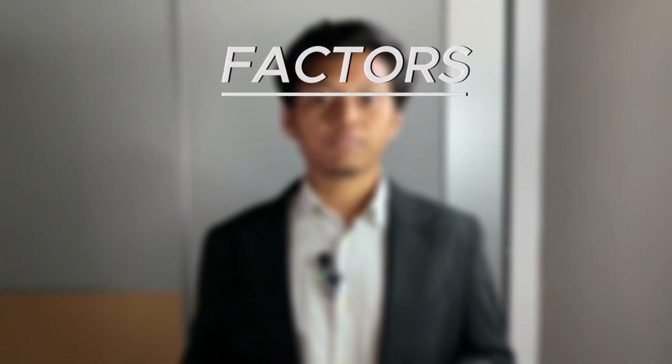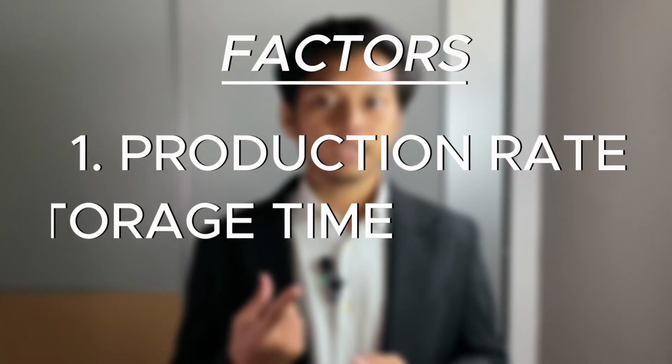Now let's talk about the tank sizing, which depends on the production rate, storage time, and the safety buffer. To find the tank's capacity, we multiply the production volume by the intended storage period and then add a 10 to 20% buffer. This buffer is crucial. It accounts for any unexpected production surge and prevents overflow, ensuring safe operations.